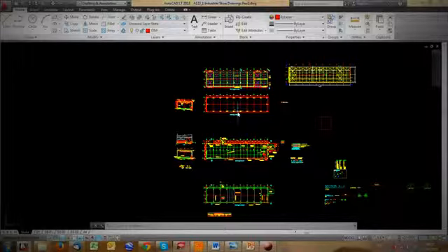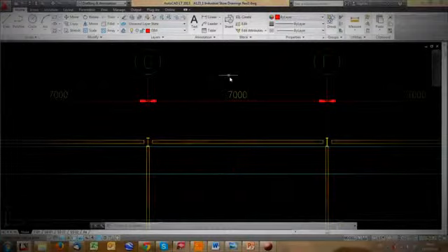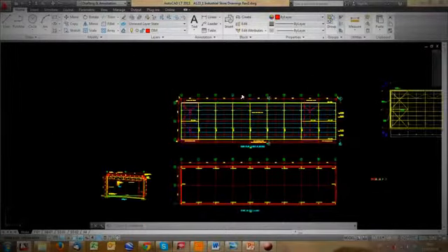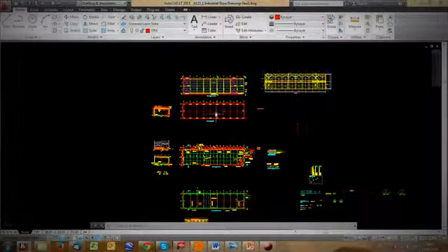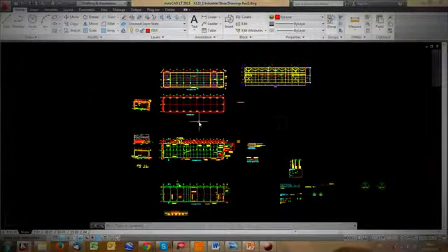What you draw here needs to correspond, though, to whatever units you are using, and that must be set up when you start the drawing, whether 1 unit is 1 inch, 1 unit is 1 kilometer, 1 unit is 1 millimeter. We are doing everything here in normal standard metric units with 1 unit equals 1 millimeter. So that is 7 meters, that dimension you're looking at right now. So be very careful that your units match before you start. That 1 unit is 1 millimeter.